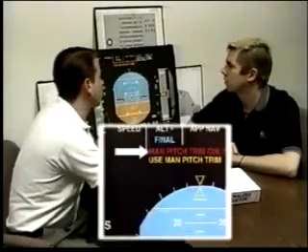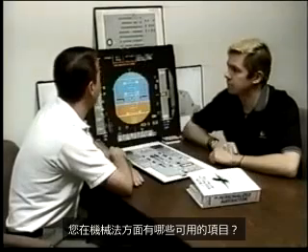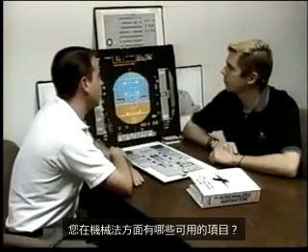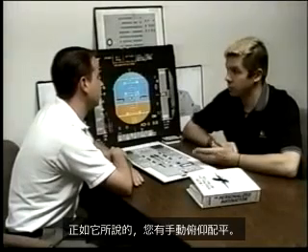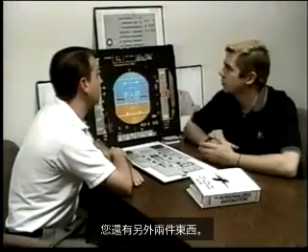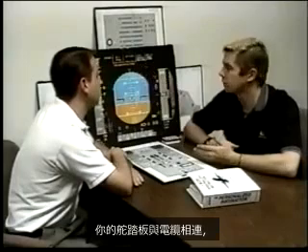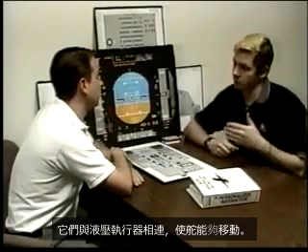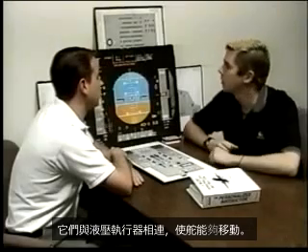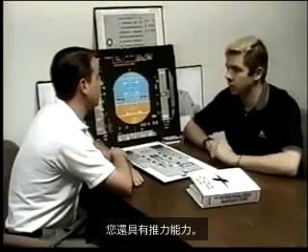What law are you in then? That gives you mechanical backup. And what are some items that you have available in mechanical law? You have manual pitch trim, as it says. You also have 2 other things. You have your rudder pedals, which are connected to cables, which are connected to hydraulic actuators, which allow the rudder to move. You also have thrust capability.